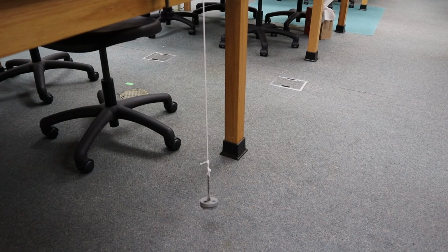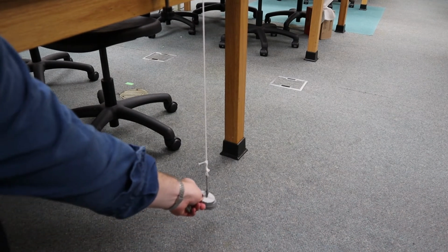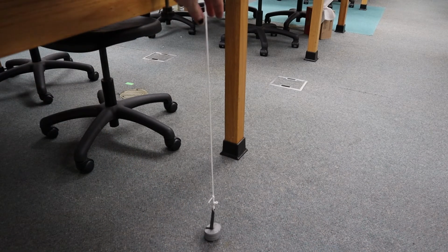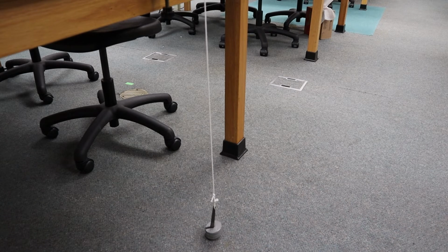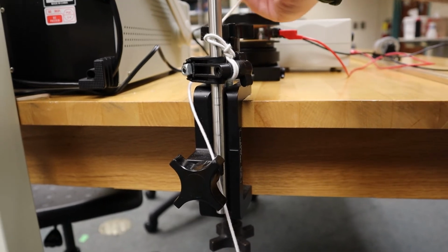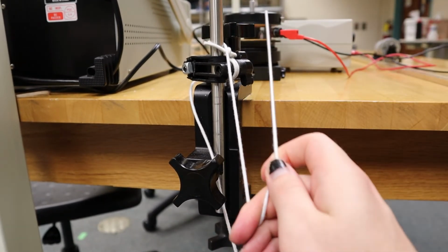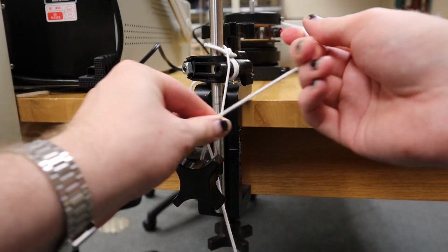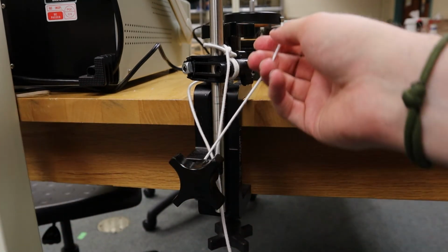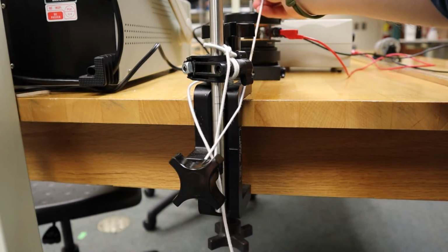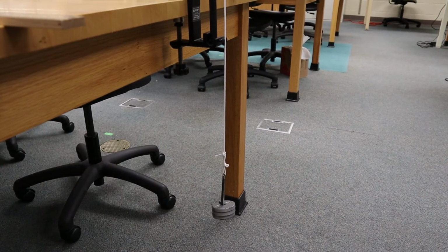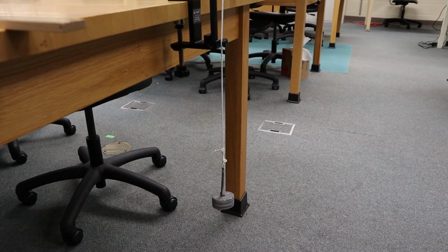There's a good chance that during your trials you will add enough mass to cause the weight hanger to touch the floor. We cannot record data during this, but there is a simple fix. All we need to do is pull the string on the mechanical driver side and wind it around the bracket that holds the pulley onto the table. Please make sure to not change the actual length between the mechanical driver and the pulley. Now our hanger will be suspended in the air and we can continue taking data.